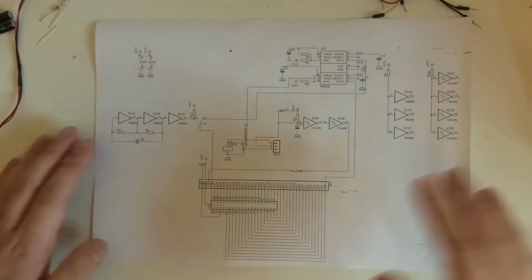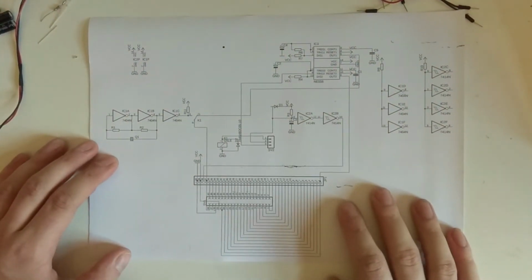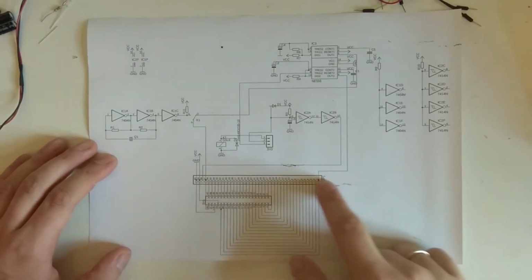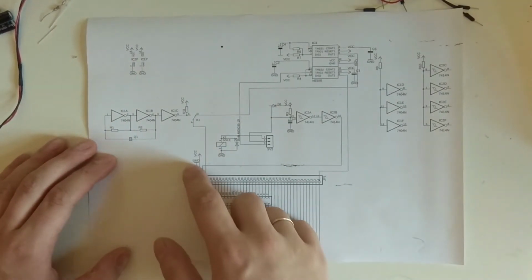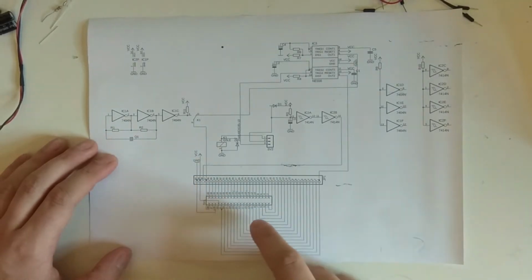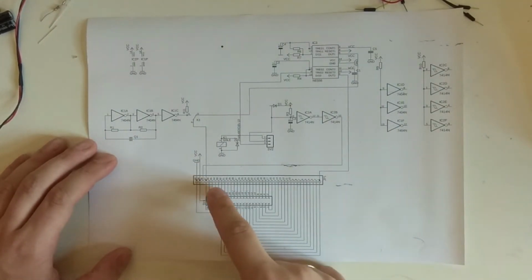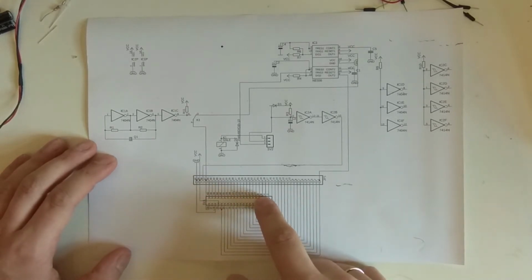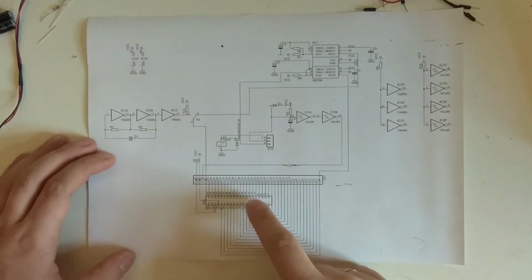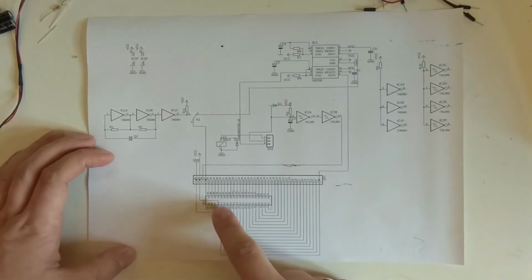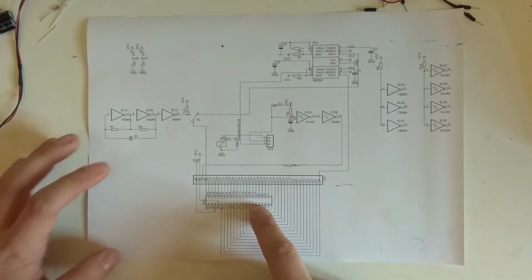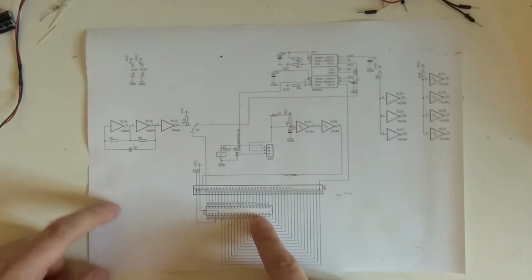So this is the schematic for what's going to be on this first board. Going to have our backplane connector down here. This just supplies ground and VCC, and then I'll basically duplicate all the lines from here to another connector that's going to sit on the board, and this is going to go off to the front panel, so we can just get all the data lines and everything for the LEDs on the front panel.